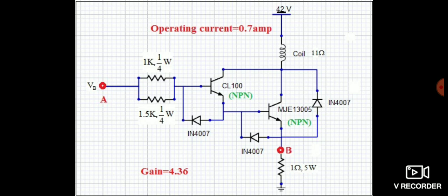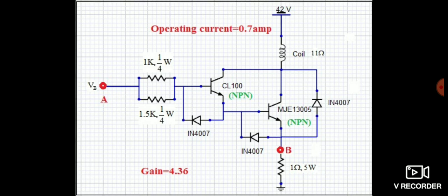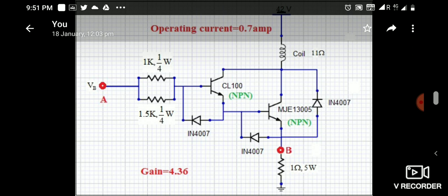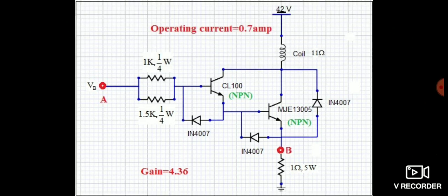We will have to check the data sheets of the transistors and pick ones that fulfill our characteristics, because we need 0.9 ampere, and there are other things like the base emitter voltage, cutoff and saturation. In data sheets everything is provided. It will start to flow current when it gets a small base voltage.